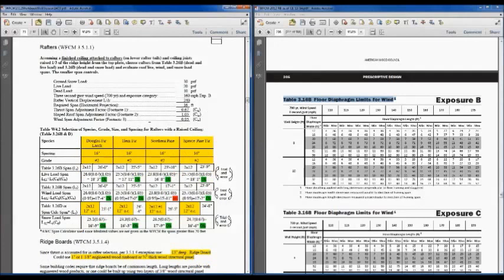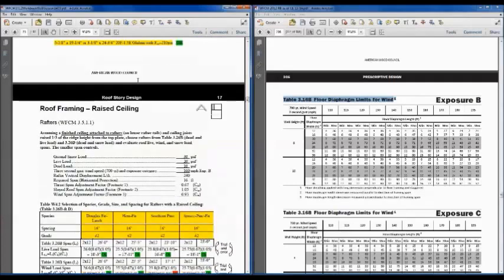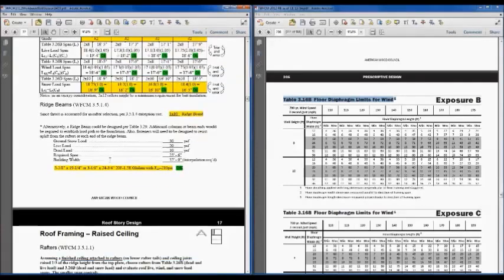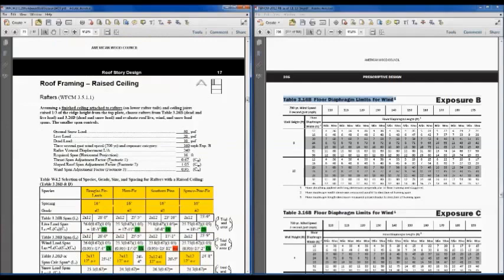And the big difference, too, is that you're dealing with a system with the ties that span from wall to wall, as opposed to rafters spanning from the wall to the ridge, which then take the load out to the... Correct. That's correct. So a ridge beam allows you to get rid of that thrust load that's pushing the walls out. Yeah. Yep.